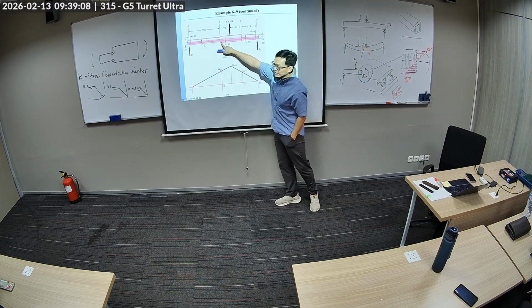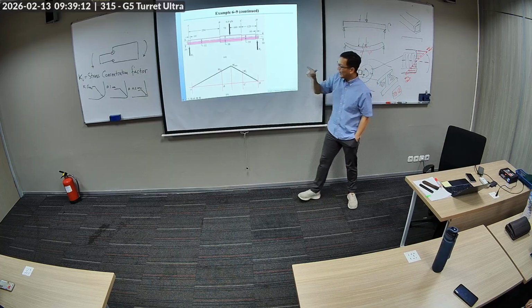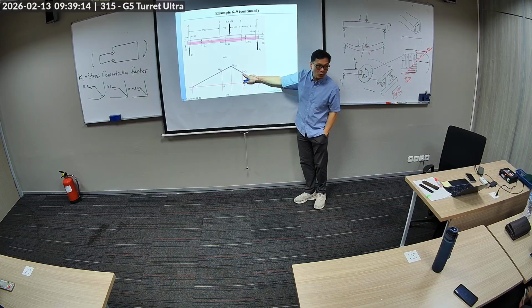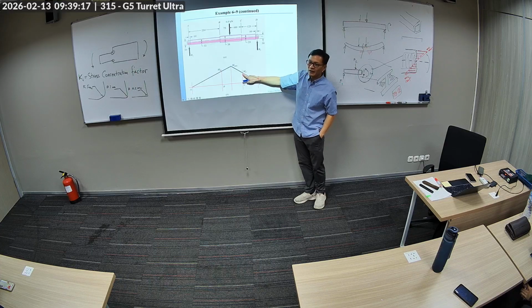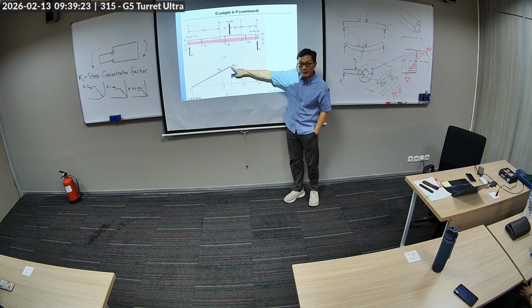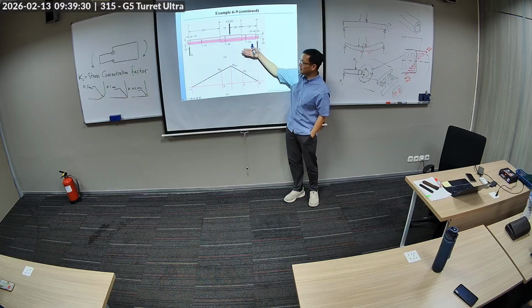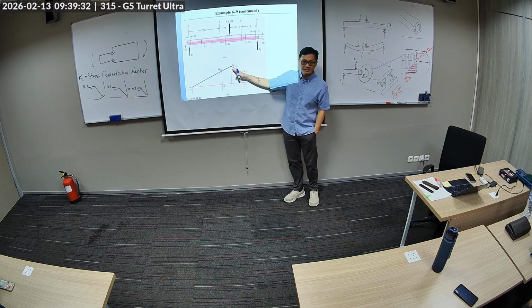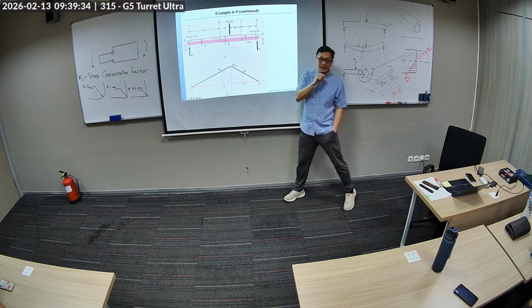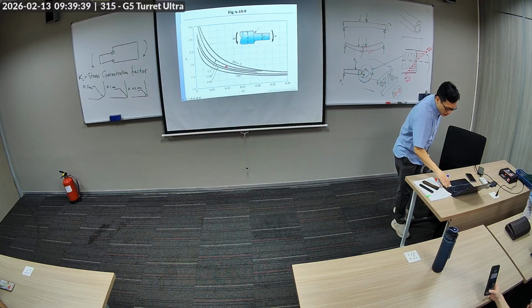Because MB at this point, or MC at this point, is going to be multiplied by 1.7, 2.0, 2.5. So the effect from MC, even though the moment is less than M max, is going to be multiplied 2 times, 3 times over, which will result in greater effect than M max, even though M max looks like it's greater.